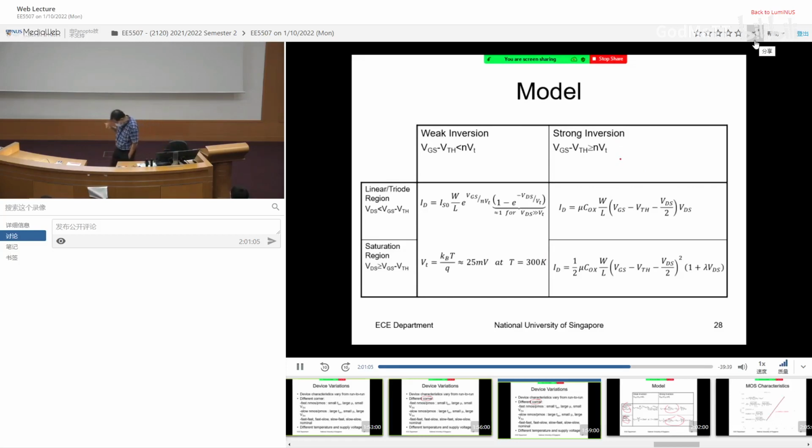Now, model. Transistors, usually we design to operate in strong inversion. Okay, strong inversion. So the square law device, saturation region and linear region apply. So this is what you commonly look at for the equations. One is in the square law region, another is in the linear region. Now, nowadays, there are a lot of low power applications. You see ridiculous things. People design amplifiers working at 4 nanoampere. It's true. Okay, the ECG amplifier consuming 4 nanowatt. They build the op-amp together with the ADC, all consuming 4 nanowatt. Ridiculous.